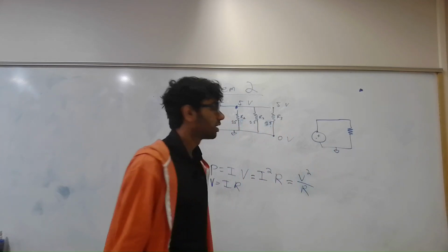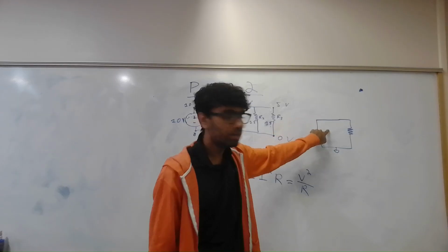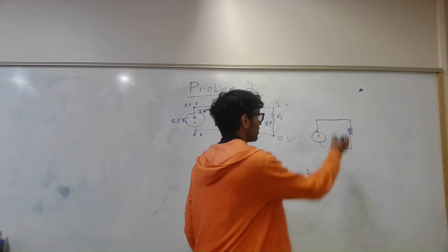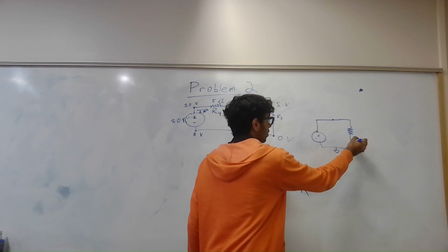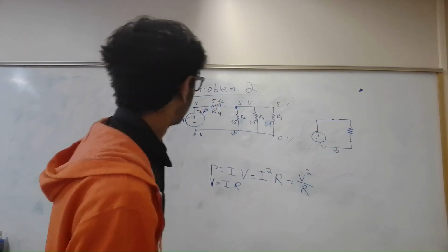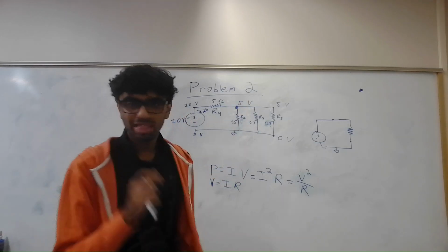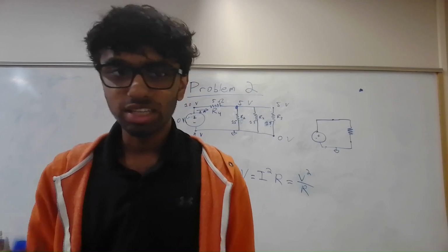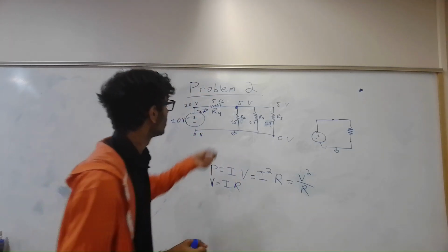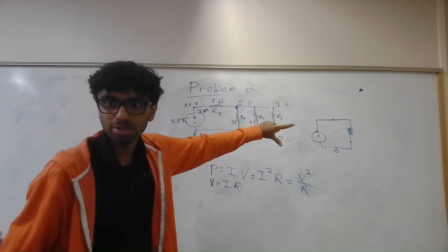And we said current going into this point on the wire has to be the same going out of this point, just an arbitrary point right there, or right there, wherever. That always has to be true. But what if that point has a third connection? That still holds true. What goes in must come out. It's just now what goes in splits into two things that come out, okay?